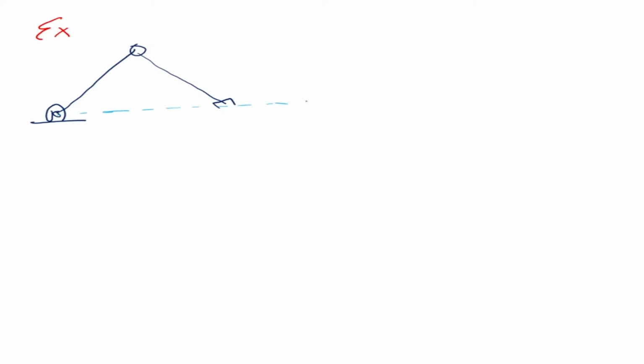Okay, so what we are seeing is that when it is here, then the manipulator will be somewhere like this. When it is becoming stretched out, it is going to get more stretched out. So that is the way it is going to go, right? So what we are seeing is there is a change of theta, and if there is a change in theta, then the value of determinant of J is going to change. You know that. So now what is the question?